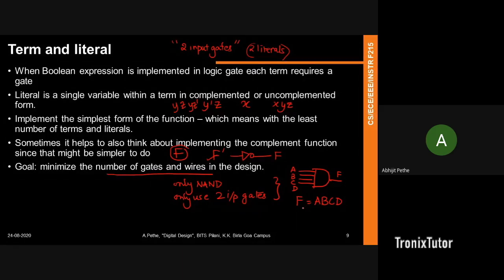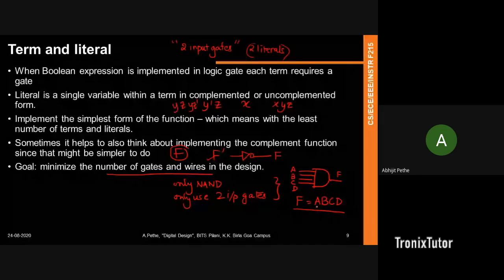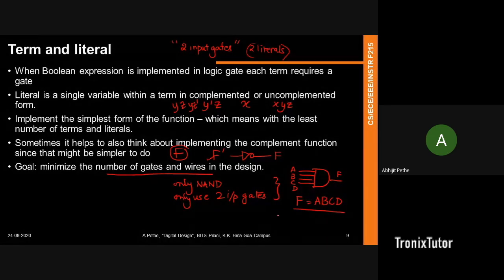In this class you don't have the background to understand this, but a gate like this would be a bad implementation in electronic design, because this gate will be much slower than a 2-input gate. As you start looking at 6-input, 7-input AND gates, they don't make sense. So you'll rather implement it something like this: as 3 AND gates, which are basically 3 2-input AND gates, right?